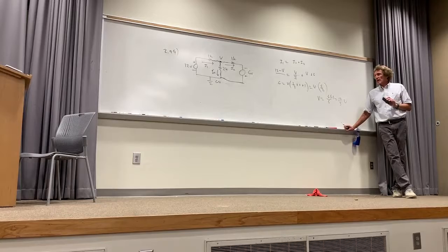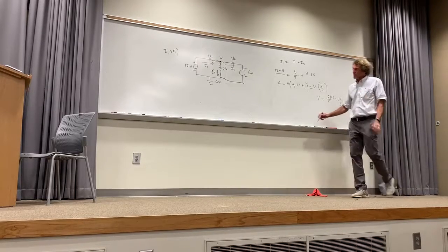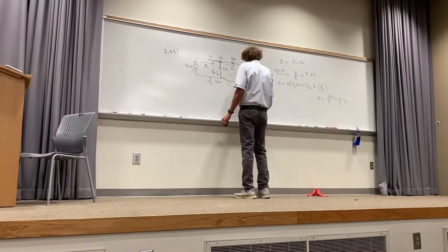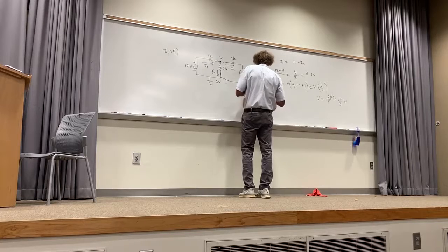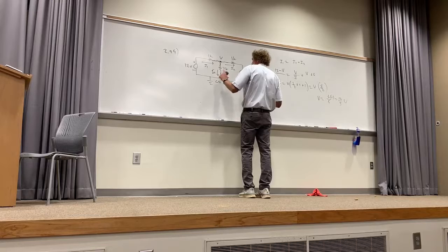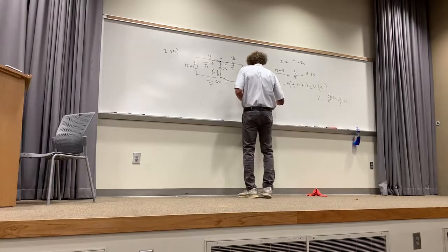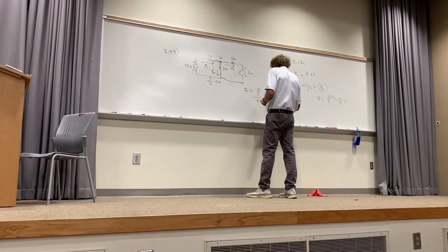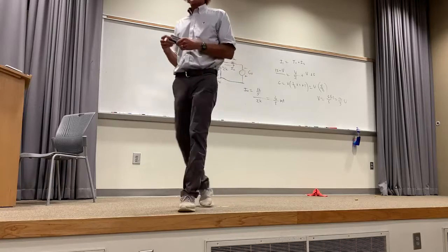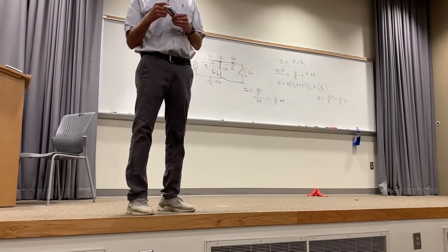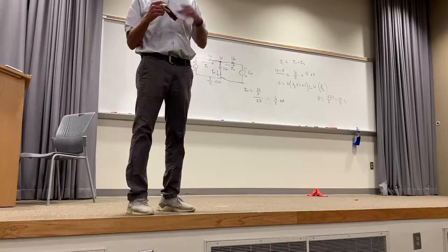All right, now that I have that, I'm after the current. What do I do? If that's the voltage here, what's the current? I naught. People? It's simply that voltage, 12/5, divided by 2K. And that would be simply what? 6/5 milliamps. Because 1 over K, 1 over 1,000 is 10 to the minus third. 10 to the minus third is milli, right, class? And the units of current are amps. How many see this right here?